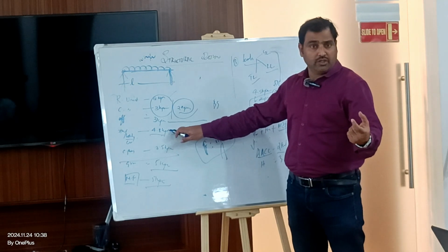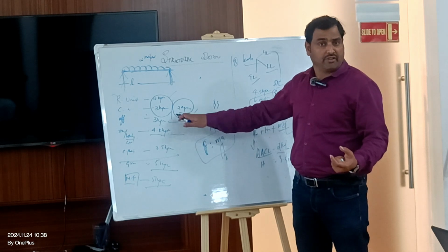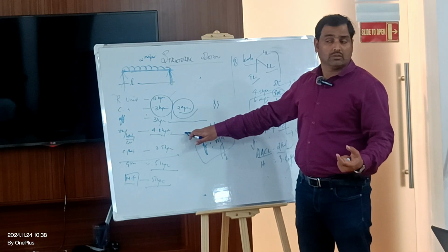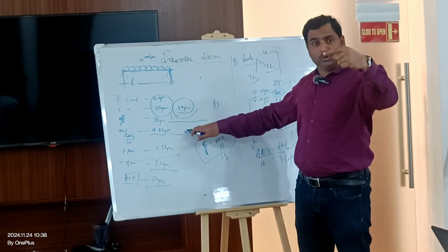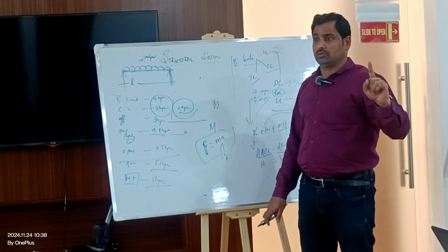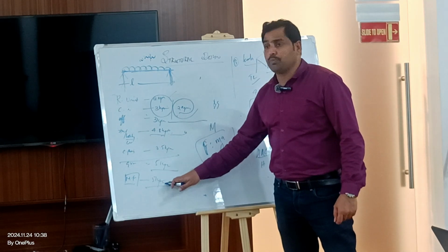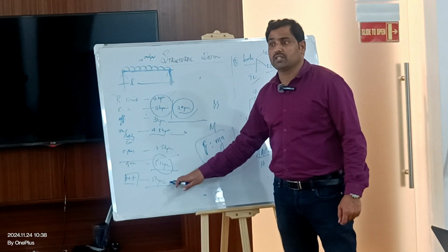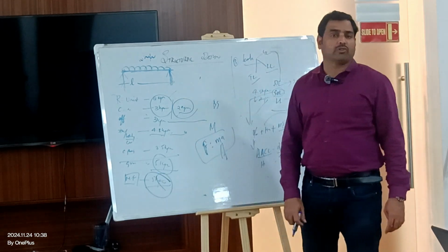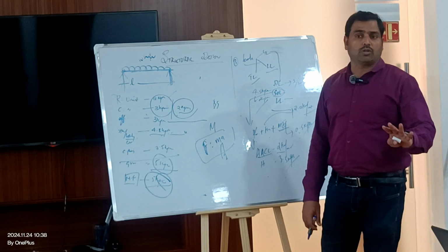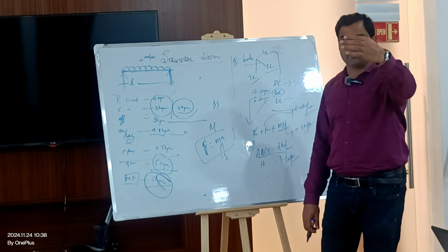When the live load is less than 5, you can only consider 25%. When it is 5 or more, you need to consider 50%. If it is more than 10, then you need to consider 100%. Because loads of more than 5 will have only two places, gym and food court, and equipment for steel structure. But normal MEP load will be more than 5 only, like 7 or 7.5.